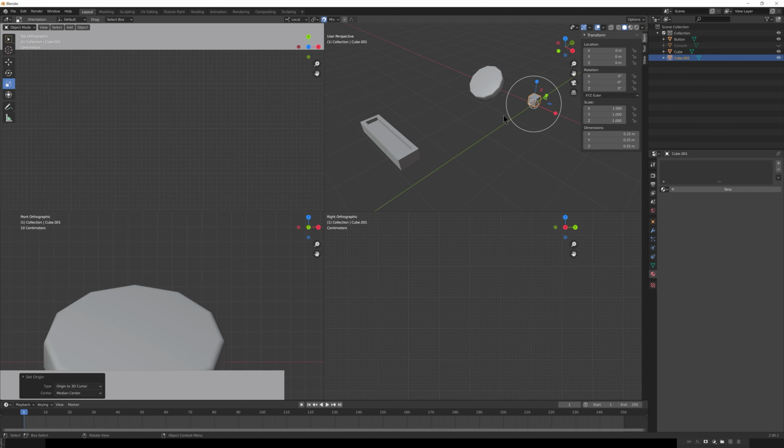If you're creating a human being, you probably won't have the ability to know that it's exactly 0.25 in the center of some object. In that case, you can use some of the snapping tools to snap along the different edges, sizes, and use constraining to get it very close, if not exactly dead on where you want it to be. Now that we've done that, we can go ahead, move this object over here onto this object here.